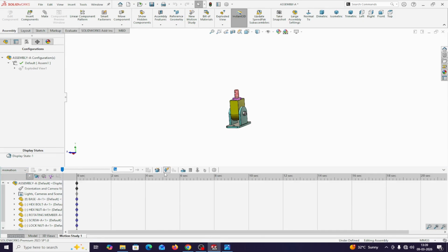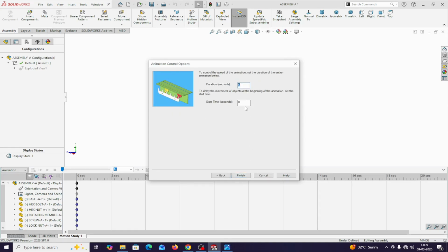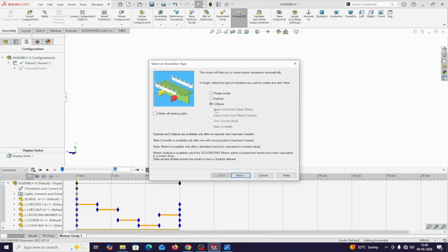Now here you will find this one, the animation wizard. The animation wizard will open, explode it. Next, give a suitable time, suppose I am giving 6 seconds for exploding. This one, start time 0, because the start time is 0. Finish. Again animation wizard. Now this time collapse.